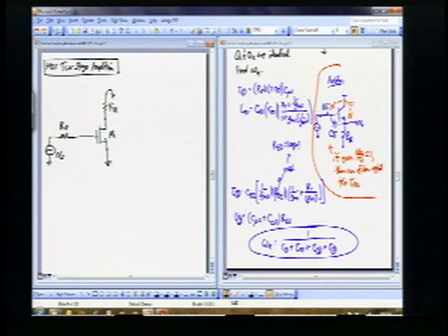And this then is going to drive another stage that is loaded with a resistance RS2. And I'm going to take my output right here. And this is a common drain type configuration, which is just like a common collector type configuration. This is M2.